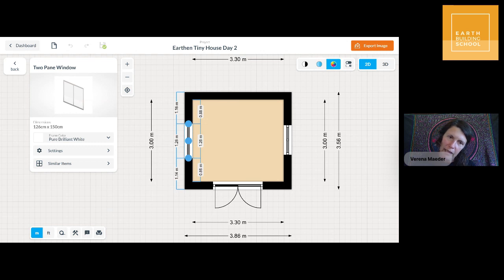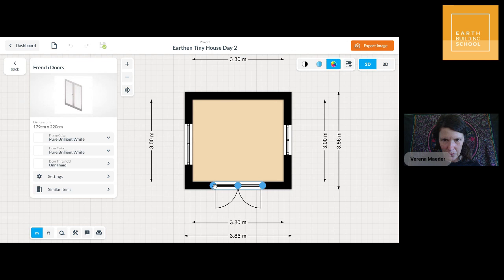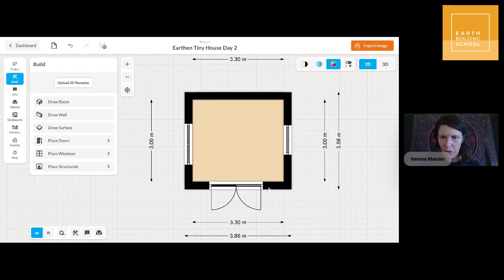And if you look at the outside measurement of the corner there, you can go down to 0.9, and that gives you a strong enough corner. And then here we might leave it, and here again we check the corner, make sure that it is a minimum of 0.9, but I also actually what I'm checking is that it is within a brick module, because I don't want to cut bricks so much. So 0.9 works.